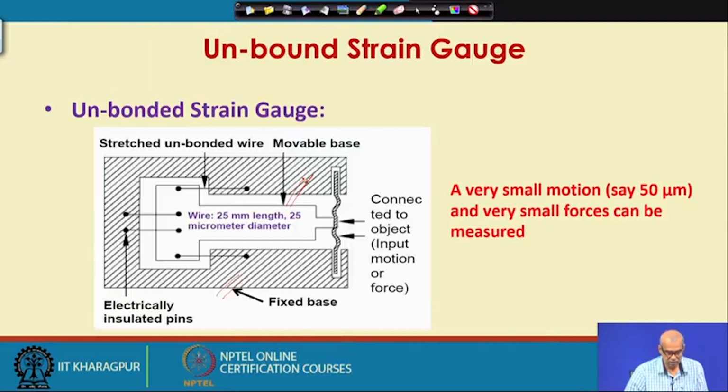There is a set of electrical wires, they are strain gauge wires, say made of copper nickel alloy or chrome nickel alloy, and so forth. Now, here we show a set of 4 wires. These 4 wires are preloaded and connected onto this frame as shown.